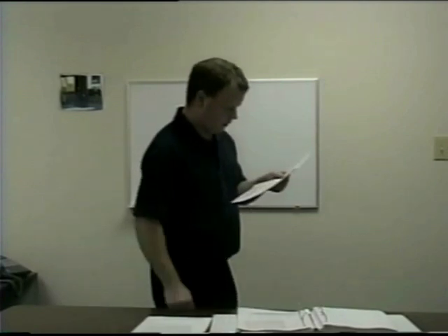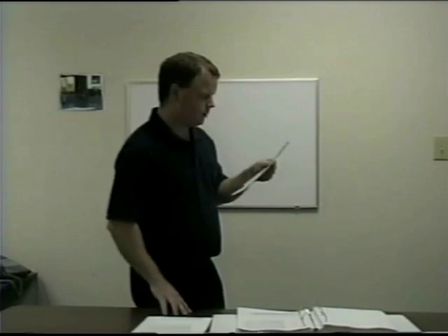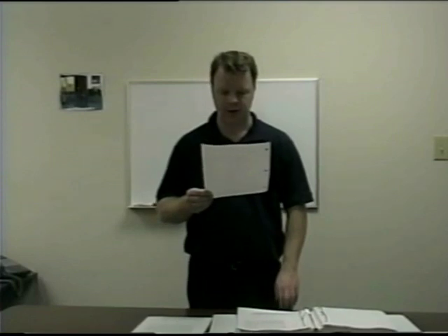Wood flooring. Verify joints are driven up tight, tongue undamaged. Verify sleepers are of material required and set securely anchored over subsurface required and ventilation more effective. Verify interior surfaces such as plaster, concrete, and masonry are dry. Obtain moisture meter test if required. Verify areas to receive flooring are closed in and adequate temperature above 50 degrees is provided.